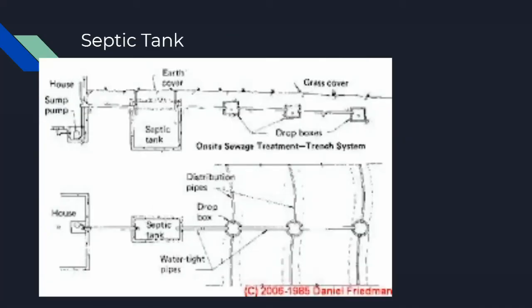And then this shows a septic tank, which is a really important part of the sewage system. The septic tank filters out the waste and turns it into sludge at the bottom and collects oil and stuff on top. And yeah, it's really important that everything's shown and covered on the site plan map. Otherwise, it won't work properly, or else you won't even have the proper permits to build it. So yeah.